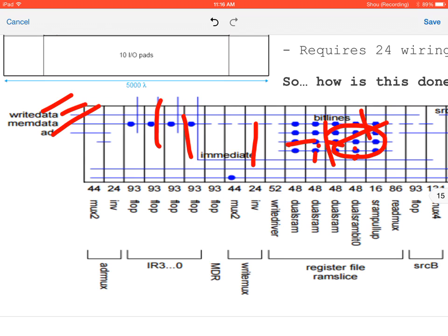Now we have all the control signals coming through. As the 8 bits go through the specific portion of the data path, you can say, all right, this control signal will manipulate it in this manner, and this control signal won't manipulate it in this manner because this is 0, and so forth. That's how it uses these control signals to implement the multi-cycle, because as you go through each portion, as it moves to the next buffer, do we need this or do we not? If not, it can go straight through that portion of the data path and move on. If so, it'll be manipulated here.